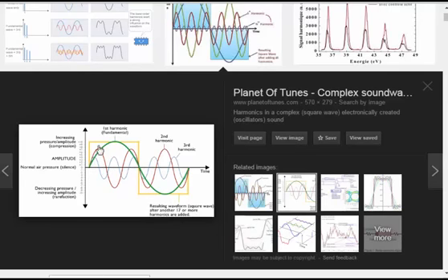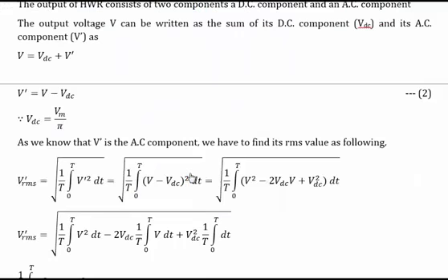If we separate another signal, we could integrate from 0 to, let's say, pi by 2, and the third would be pi by 4, likewise. But we cannot separate the composite signal, so we take the range of integration as 0 to T in generalized form, divided by T. Instead of a finite range like 0 to pi or 0 to 2 pi, we generalize, because each signal within the composite signal has a different time period.